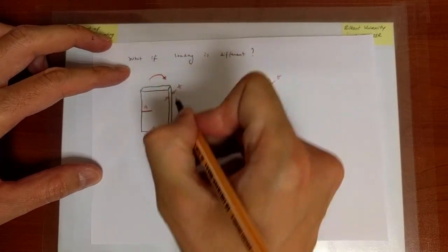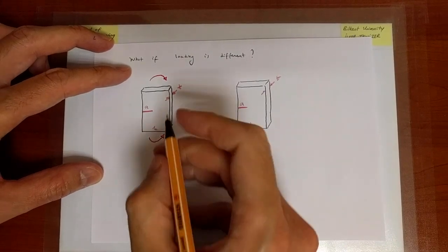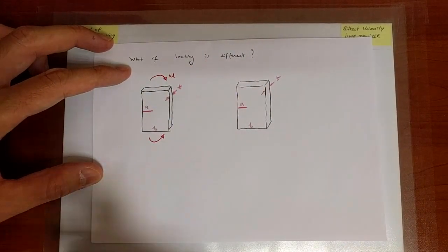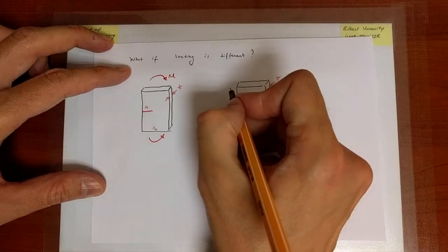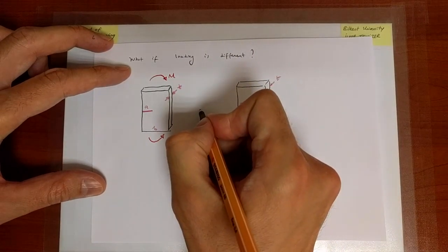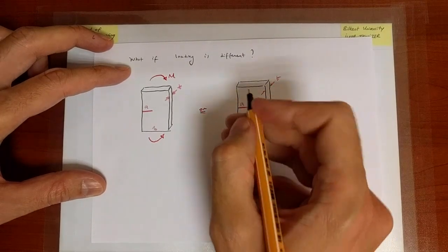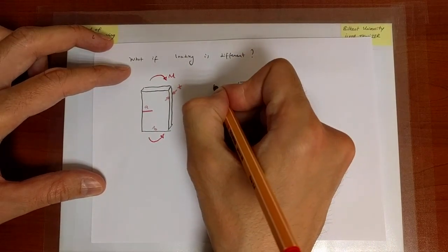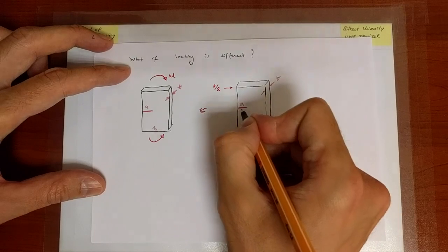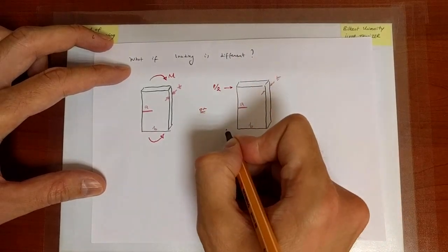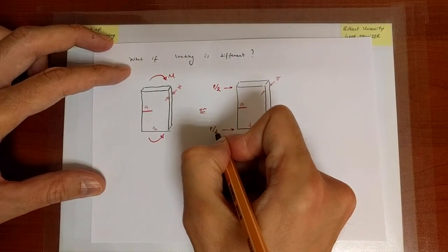So bending is only relevant in that direction. Okay, so in the other direction, we don't need to consider fracture. So in this case, I'm going to use a loading scenario that is statically equivalent at the cross section where the crack is, at least, statically equivalent to bending.